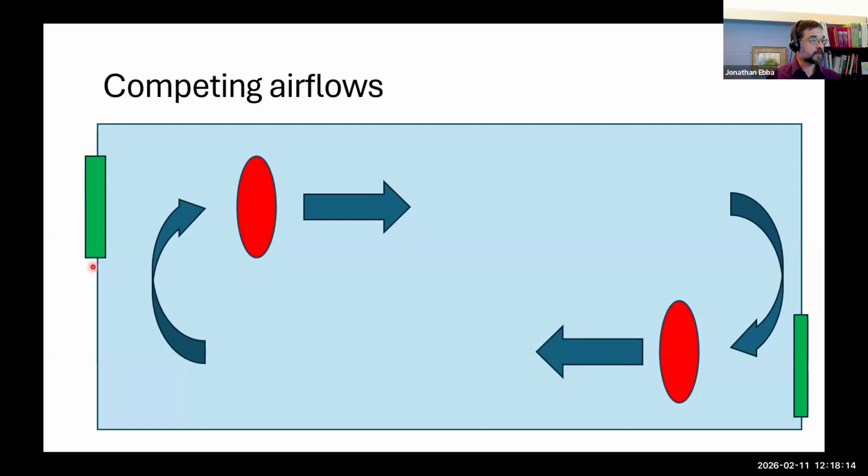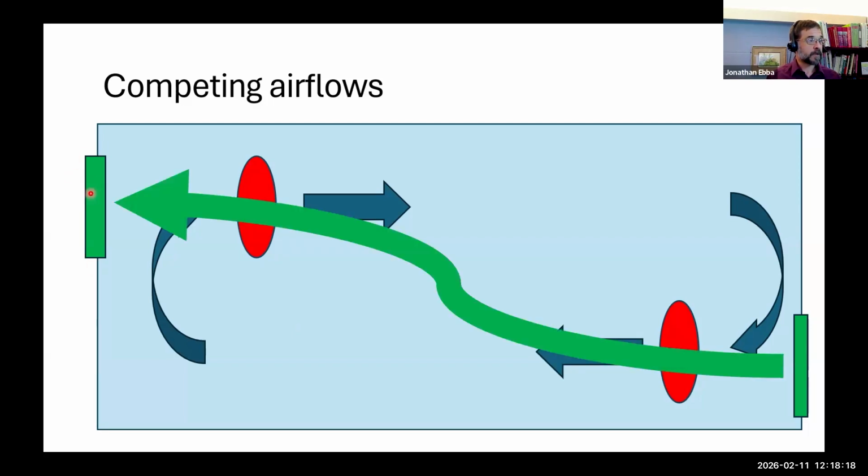In a typical horizontal airflow, in this case, we have the circuit of air traveling like this. This greenhouse has active ventilation. And so you can see what happens is when I'm venting, my ventilation airflow is competing with my horizontal airflow, and I get some turbulence here, and I'm cutting the efficiency of both of these.